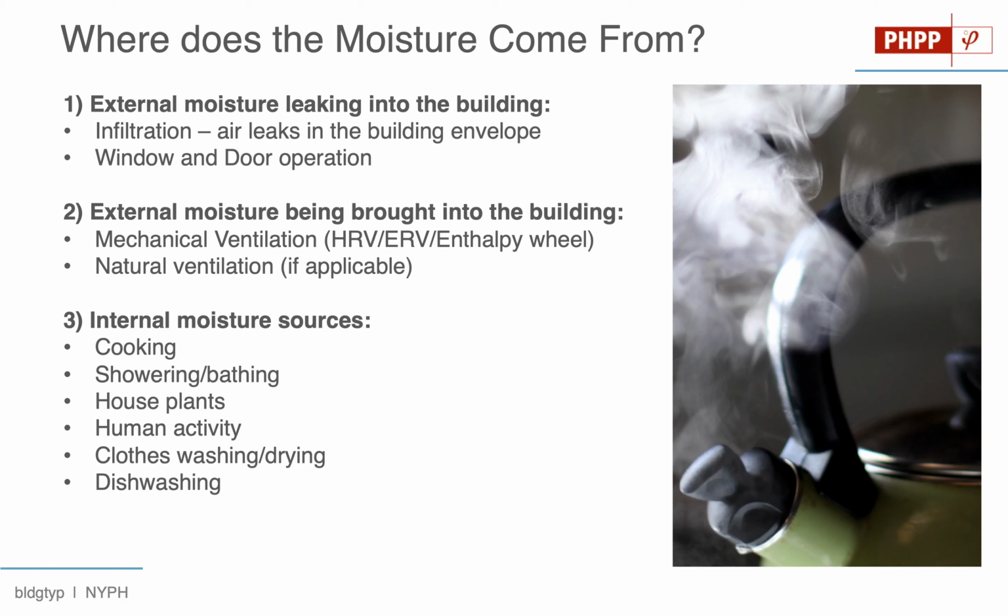And then lastly, we have a bunch of moisture from stuff that people do inside of buildings. Things like cooking, bathing, washing dishes, breathing, respirating, these types of things release moisture into the air in the building itself. So we have three distinct sources of moisture that we need to combat in order to deliver an acceptable level of humidity inside of our buildings. Remember, that acceptable level is put at 0.012 pounds of moisture per pound of dry air.